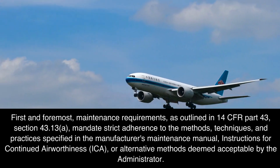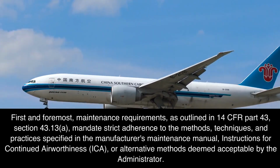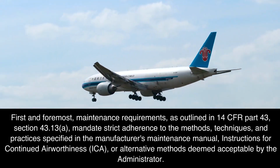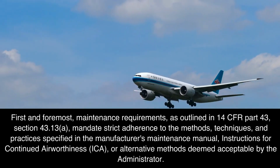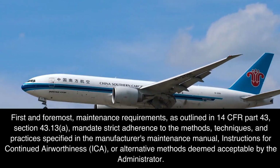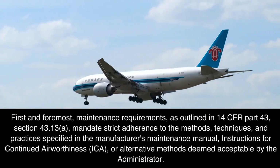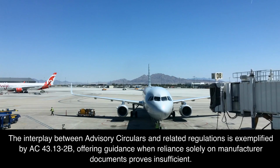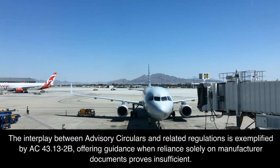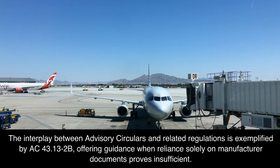First and foremost, maintenance requirements, as outlined in 14 CFR Part 43, Section 43.13(a), mandate strict adherence to the methods, techniques, and practices specified in the manufacturer's maintenance manual, instructions for continued airworthiness, ICA, or alternative methods deemed acceptable by the administrator. The interplay between advisory circulars and related regulations is exemplified by AC 43.13-2B, offering guidance when reliance solely on manufacturer documents proves insufficient.